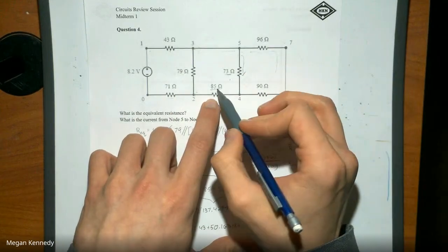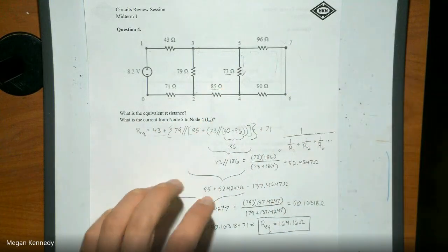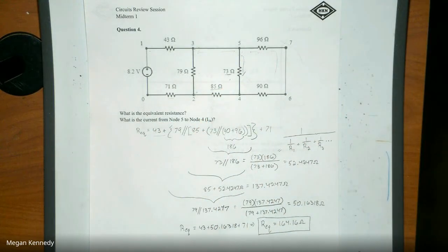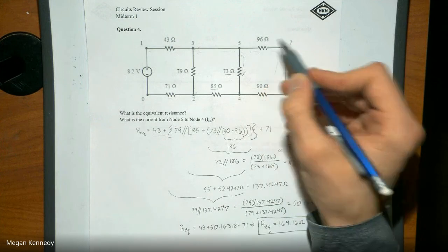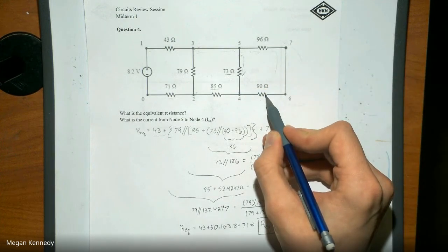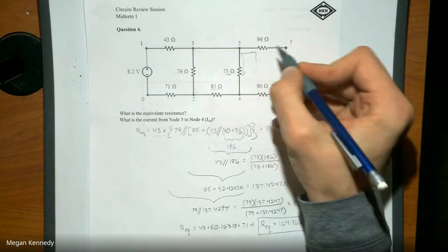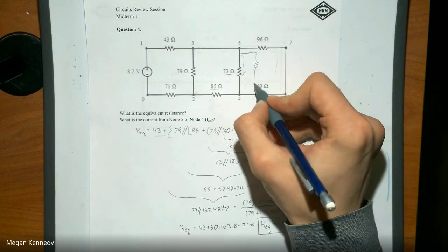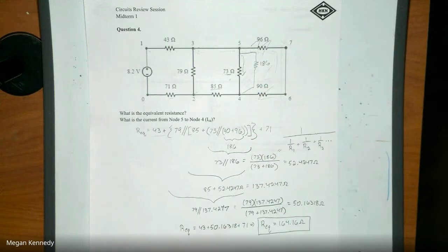And when we break that down, we end up having this 85 in series with. So if we work the other way, which I think would make more sense to start off with, that's what I started to learn with. Looking at it, we have this 96 ohm resistor in series with this 91, right? So we can have an equivalent circuit. If we ignore all that with this 186, those are in series.